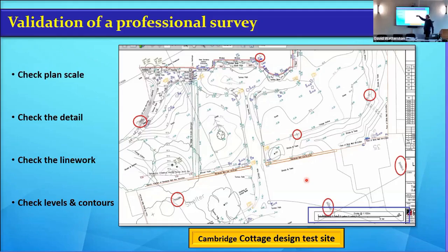DPC is 5.48. You understand what DPC is? Damp proof course. And so that's the black line that you'll get round the edge of a building. It's generally a bit above floor level. They could be slate. They could be PVC, or I don't know, they probably come up with other materials. And the reason you notice it is the joint, the difference between the brickwork, is usually larger because they've got a bed. They put the DPC on it, and then they put another bed before they put the next bricks on. So you're going to get it a bit fat.